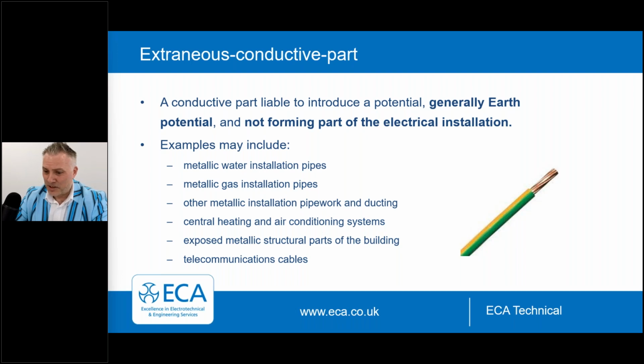And there's a note on our certificates that we can bond those with the permission of the owner of the cable. If not, it can be reported as a departure on the appropriate certificate. So an extraneous part doesn't change if it's metallic and it goes through the earth. Generally, it's what we class as earthy, and it's liable to introduce potential into that installation.